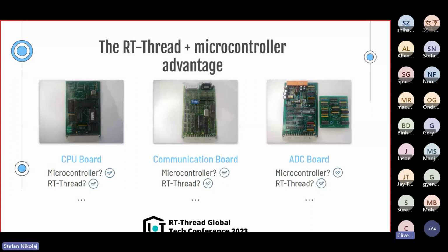Even though the total number of ICs is quite extensive, this PLC dates from only 2004, even though the design does look like it's older. And nowadays, though, a single microcontroller running RT-thread can replace all of these 3 processing boards and offer enhanced functionality at a lower cost while occupying significantly less board space.